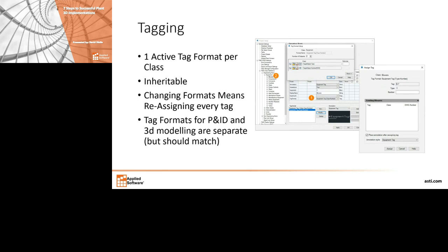Now, it's like a 2-second process, but it's still a 2-second process on everything that they put on a P&ID or in a model. There are tools, there has been some code put out that automate some of this, but even in those scenarios, it's been hit or miss in some situations because it's not fully supported. So there's still cases where even if you do find the plugin that automates some of the retagging, you end up manually updating some of the tags.